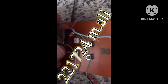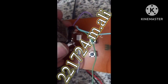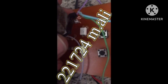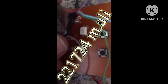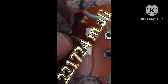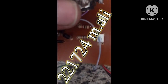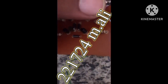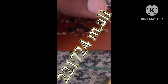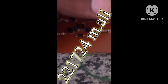We use two buttons: for one press they move in clockwise, and the other button we press they move anti-clockwise. The two optocouplers are used to reduce the damage and control and stop the current flowing in the backward direction. These are resistors, and further we use an H bridge and freewheeling diodes with transistors.